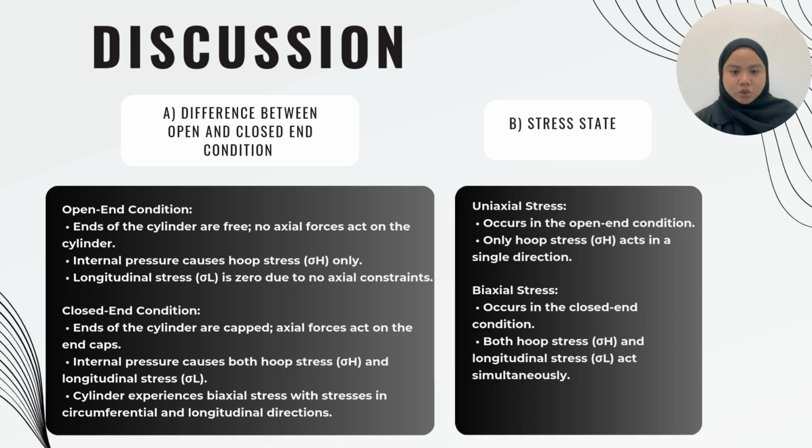For the closed-end condition, the ends of the cylinder are capped and the internal pressure applies axial forces on the end caps. This introduces both hoop stress and longitudinal stress into the cylinder. The cylinder experiences a biaxial stress state with stresses in both circumferential and longitudinal directions.